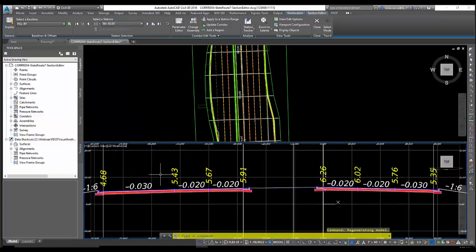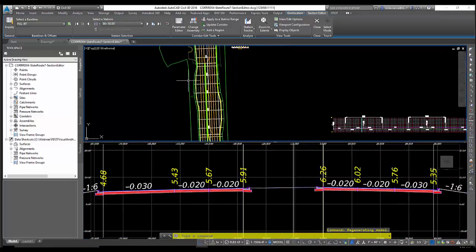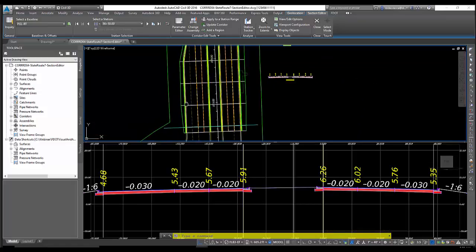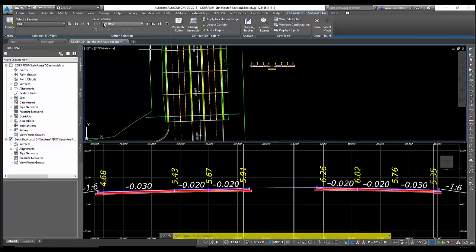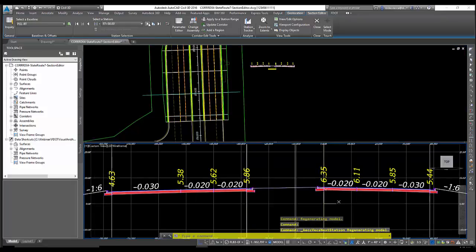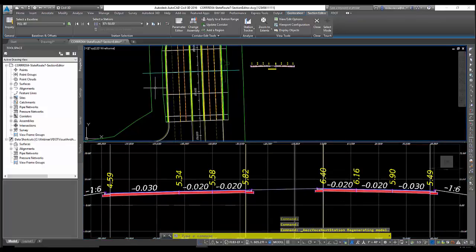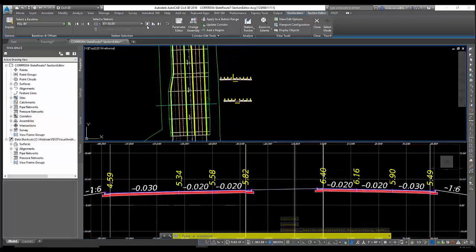And if you pick on that line, you'll see that it updates here on the bottom, and that my cyan line jumped towards the bottom. You have the option to look at stations that have had some kind of station override applied to them, which we'll look at here in a second. I believe we only have one, but I'll show you how to create some other ones. As you click on this arrow to move forward, you'll also notice that the cyan line moves forward and that your section editor down here updates accordingly.